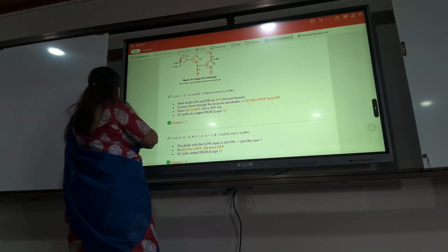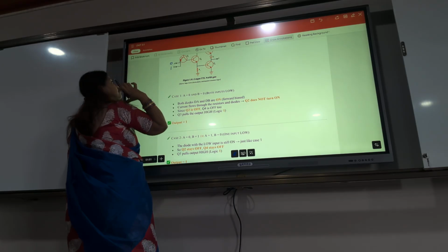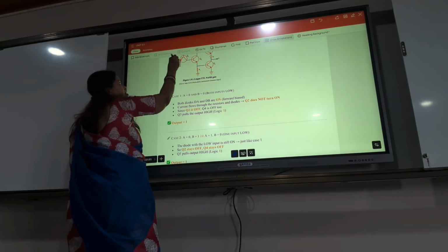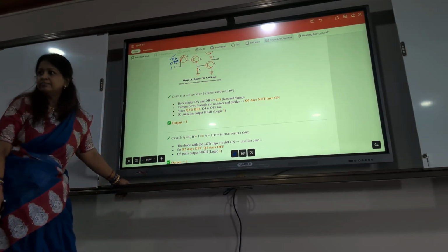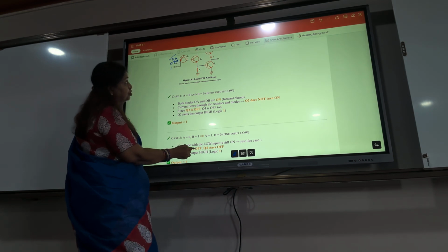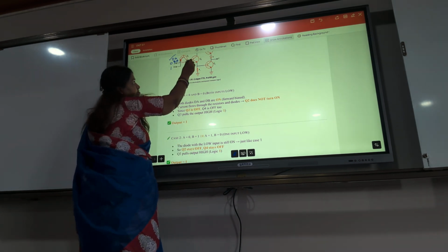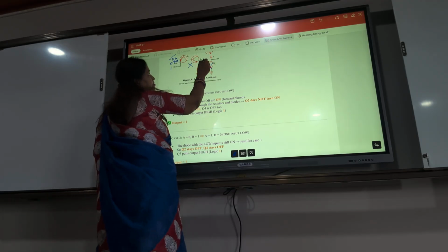0, 1. So if you consider VA, DB, this is on, it's forward biased. So what happens? Q2 stays off again. Then Q4 stays off.